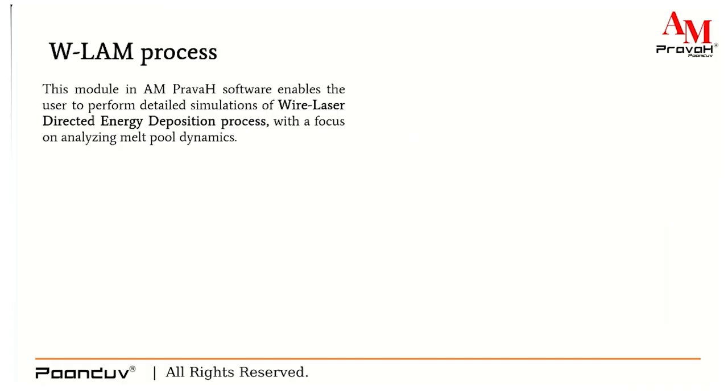So the WLAM process in PravaH software also follows the laser DED process. The module in PravaH software enables the user to perform detailed simulations of wire laser directed energy deposition process with the focus of analyzing the melt pool dynamics.